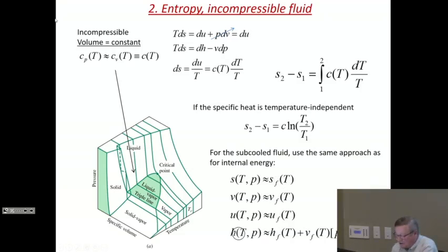We had a little correction to apply when it was enthalpy, because the pressure was there explicitly. Sometimes when the pressure difference is not too large, you ignore this. But when the pressure difference is large, you have to correct it. No such correction appears in either internal energy or entropy. Entropy here behaves like internal energy, which you actually see right here.